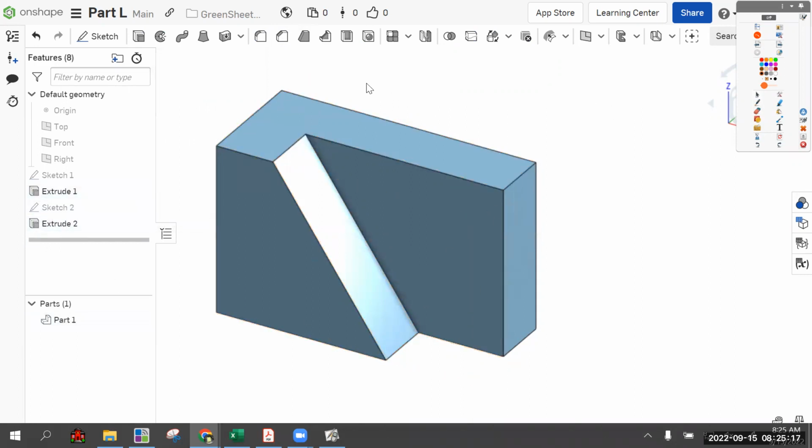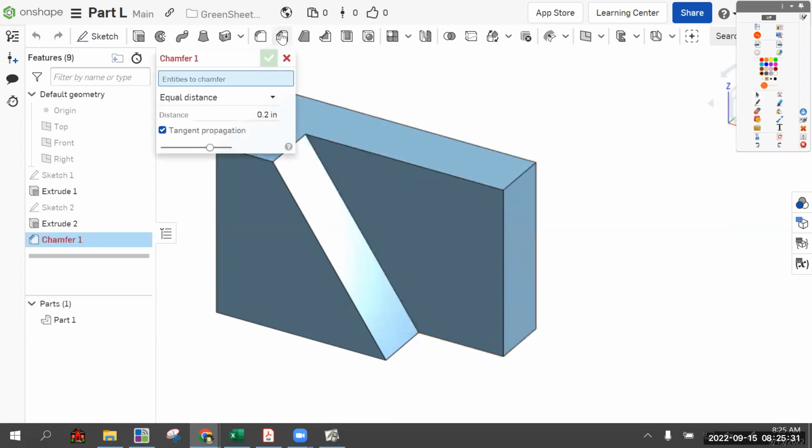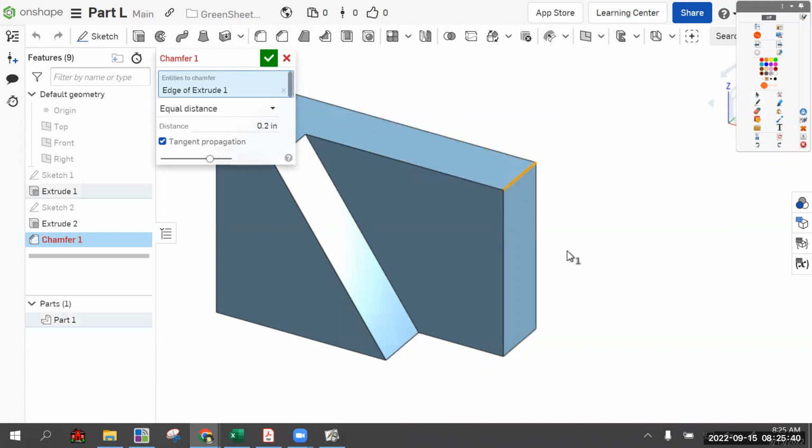We're going to go straight to a part feature, which are up here, the chamfer and fillet. Let's pronounce it fillet, not fillet. And a couple other ones don't require sketches. They're just straight part features that you can use, and you can tell from the little pictograph what it does there. It breaks the corner. And so all we need to choose is the edge that we want to knock off. And if you have it set to equidistance, which is the default setting, and you put in whatever value, that dimension of 2 inches is the distance this direction and this direction, because it's set to equidistant.